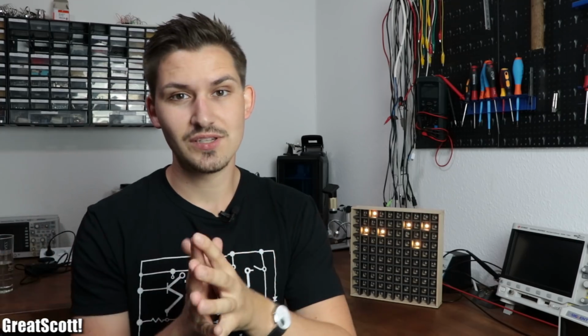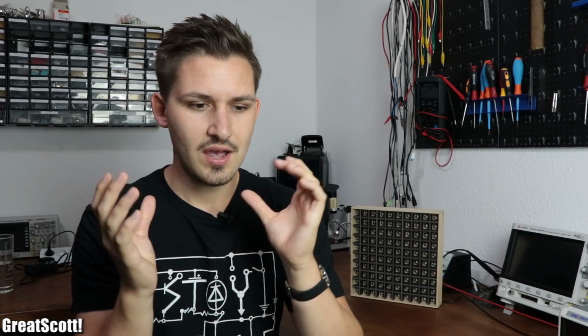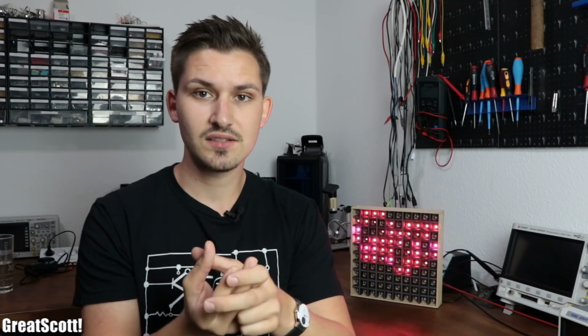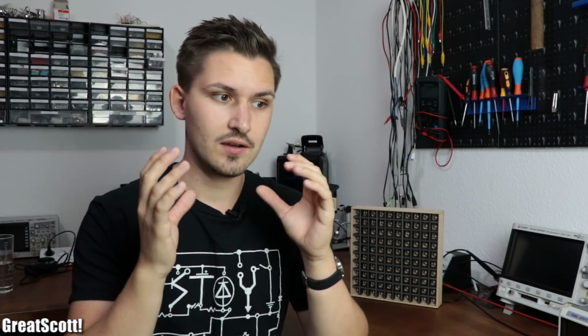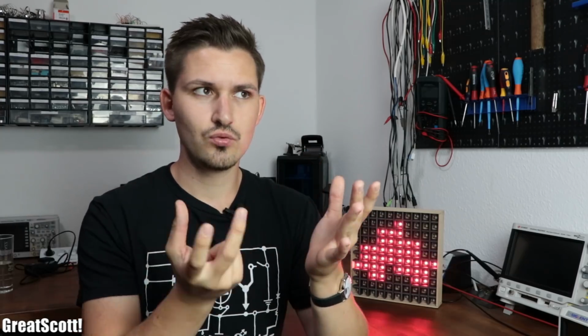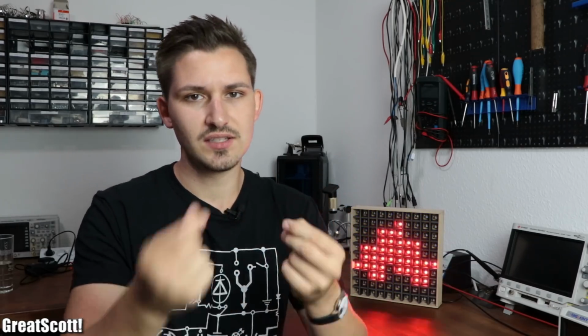So as you said, you need 7.4 volts. I would go with something like 2 18650 cells. Maybe the ones I always use, the INR 18650-25R. Maybe even in a battery holder, there are specific ones for 18650 cells, so you can swap them out later. So get the battery holder, just for 2 batteries. The charger for 2 is, I think, relatively cheap. The charger then works by charging each cell individually, since you will be taking them out and then recharging them.